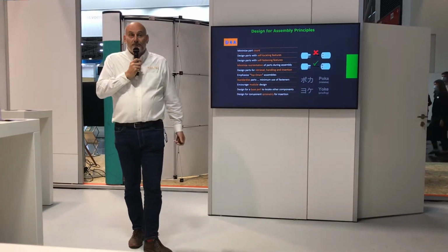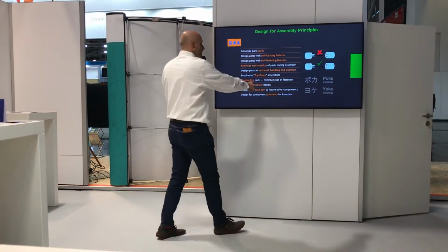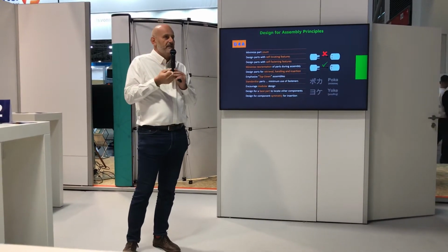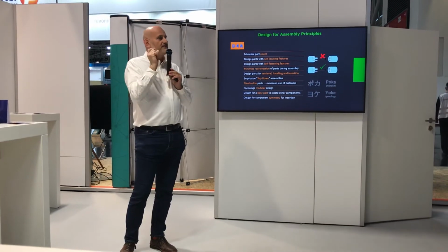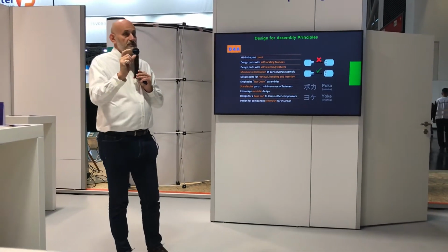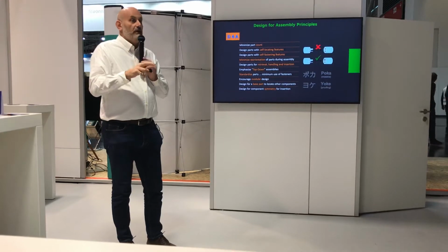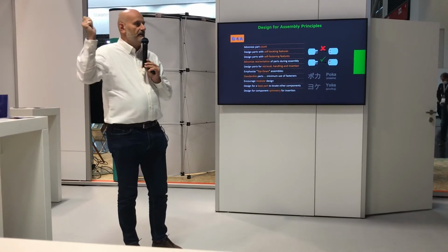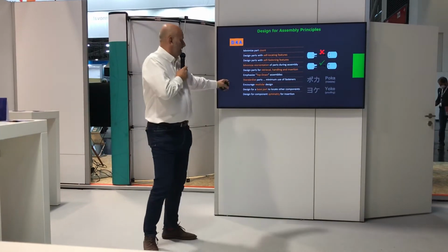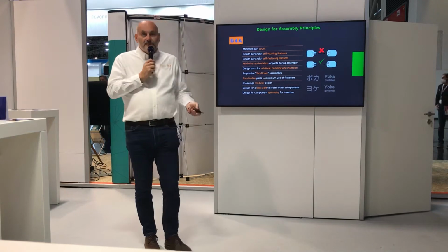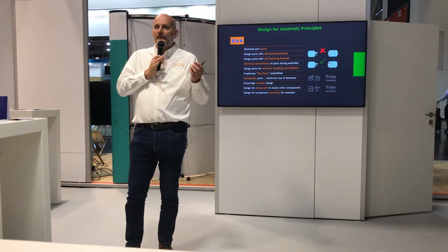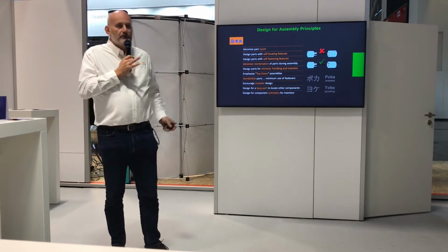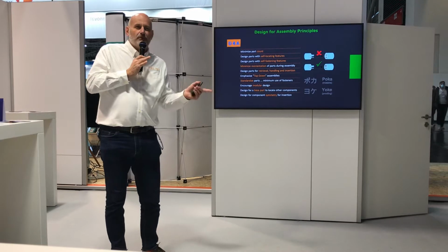Try to use standard parts in order to minimize the use of fasteners. Also, if you get to bolts and nuts, try to use one size for everything. It's cheaper to have over-dimensioned bolts and nuts than to have more than one size, because you just have one tool in your pocket and that's good for all. And modular design: if you build and design your product in a modular way, you can then simply scale up the product without having any issue of what comes first and what comes after.